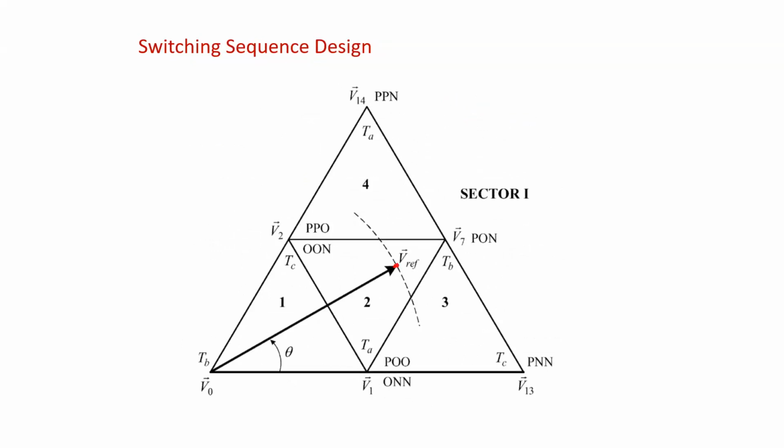So what are the nearest space vectors? We have V1 vector, V2 vector, and V7 vector. So we have 3 nearest space vectors, right? One is V1, V2 and V7. Okay. Right. So now come to our theory. What we discussed is that our objective is to reduce the neutral point voltage deviation, right?